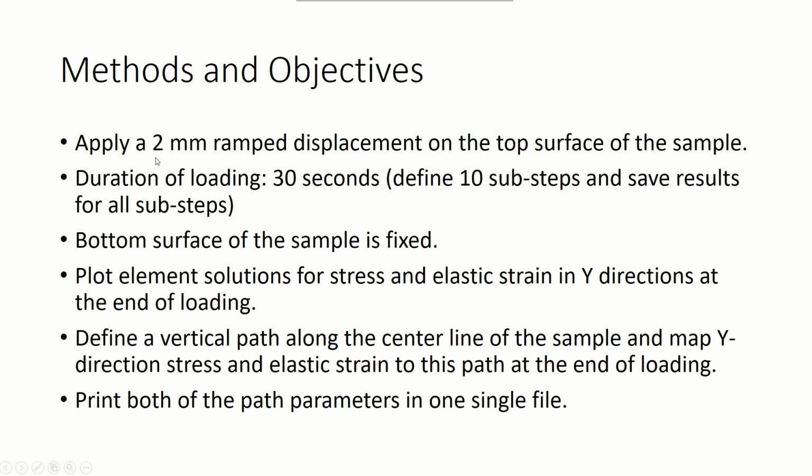We want to apply a 2 millimeter ramped displacement at the top surface over a duration of 30 seconds and define 10 sub-steps in that 30 seconds and save all the results for all the sub-steps. The bottom surface of the sample will be fixed, and then we want to plot the element solutions for stress and elastic strain in the y direction at the final load step, which is the 30th second.